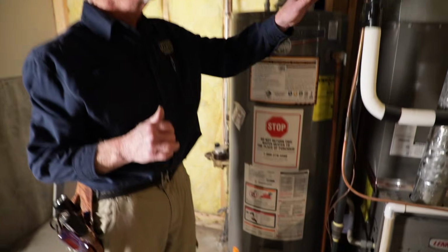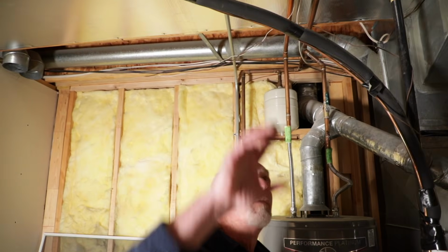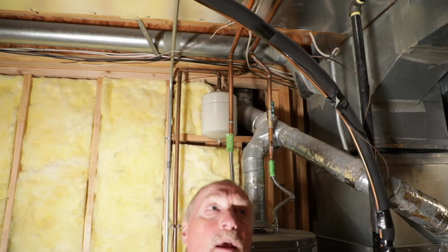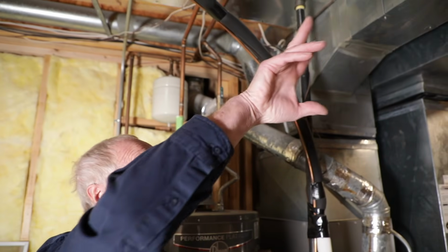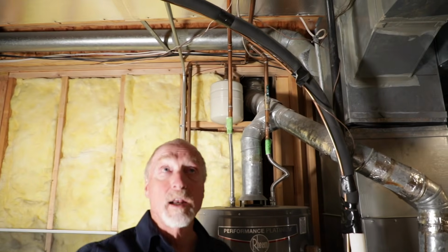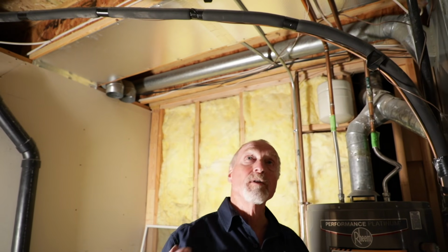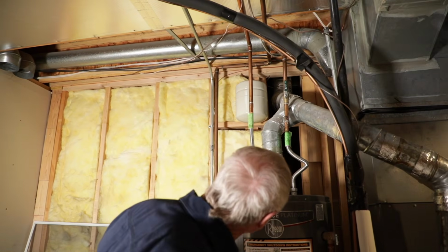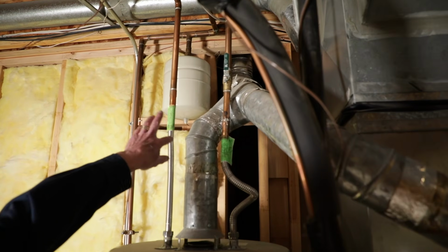So as we walk our eyes up and over our gas line, we're also looking at our copper water plumbing up here. And if you have your gas sniffer with you, you can run that along these connections and see if you get any gas leak. But again, our noses are more sensitive than gas sniffers, and we would probably be smelling it while we're standing here. While we're also here, we're checking our flue, making sure we got the proper clearances on it going up.